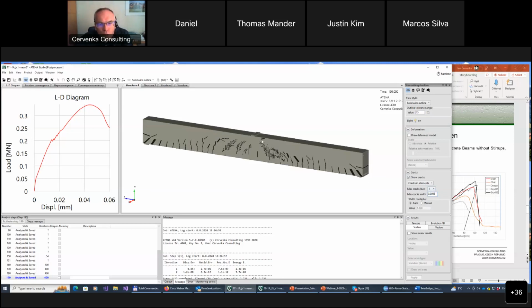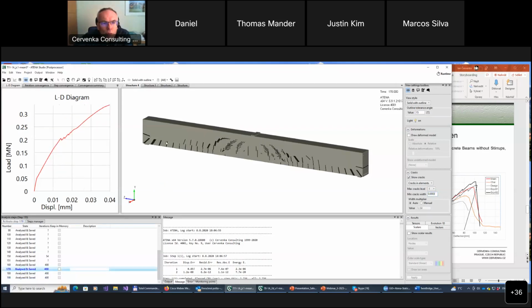Of course, now you may say the cracking is still somehow not so nice. That's because we are already quite far into the failure mode. In addition, this failure mode is not so much about cracking. It is more about crushing of concrete. But if we, for instance, go to the peak, you will start to see a much better and understandable view.